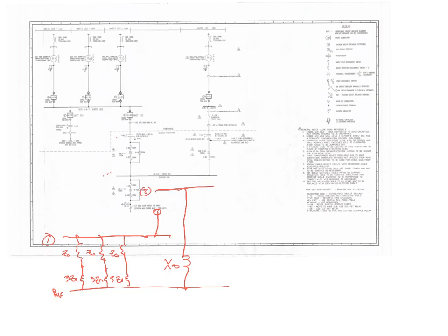That breaks it up. Now I look at my next transformer, which is delta delta. So at bus 2, I want to come off, but I cannot connect to bus 3 because the delta prevents me from connecting to bus 3. And there is no connect. Why did that happen? There is no connection between bus 3 and reference because the delta just circulates inside the delta, right?